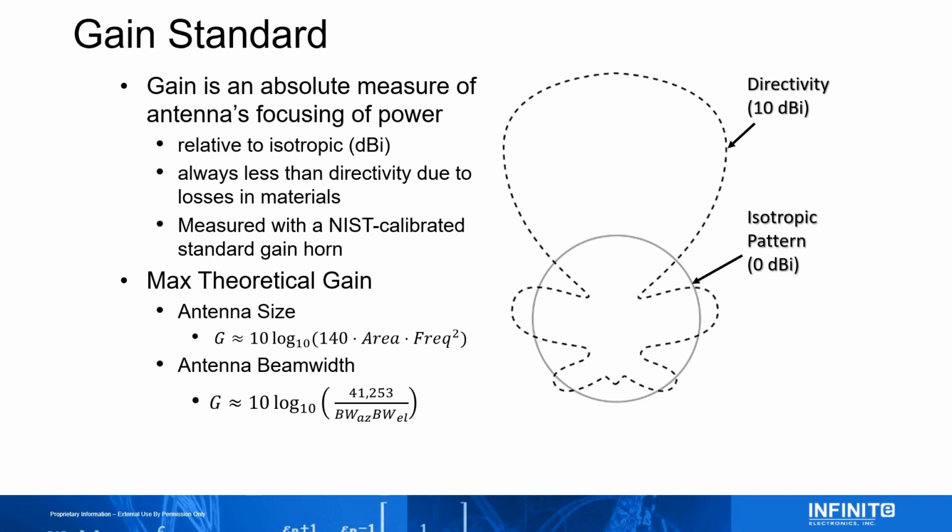The fact that you're focusing power means that you increase the directivity of the antenna, so now it's pointing in one direction. I'm showing an example of a 10 dBi directivity. Now, we're not at gain just yet. Gain is actually directivity with loss. Loss comes from your choices of materials in the antenna. It comes from your reflection at the port, so your VSWR. There are lots of different sources of loss in the antenna, but what does loss do? It decreases the directivity.